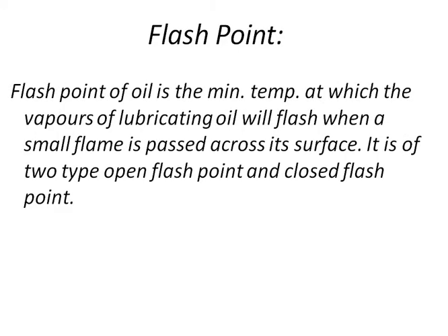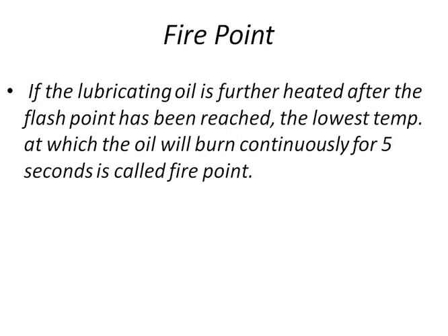Next is the flash point. You have done this experiment in the laboratory. The flash point of oil is the minimum temperature at which the vapor of lubricating oil will flash when a small flame is passed across its surface. Then the fire point. If the lubricating oil is further heated after the flash point has been reached, the lowest temperature at which the oil will burn continuously for 5 seconds is called the fire point.